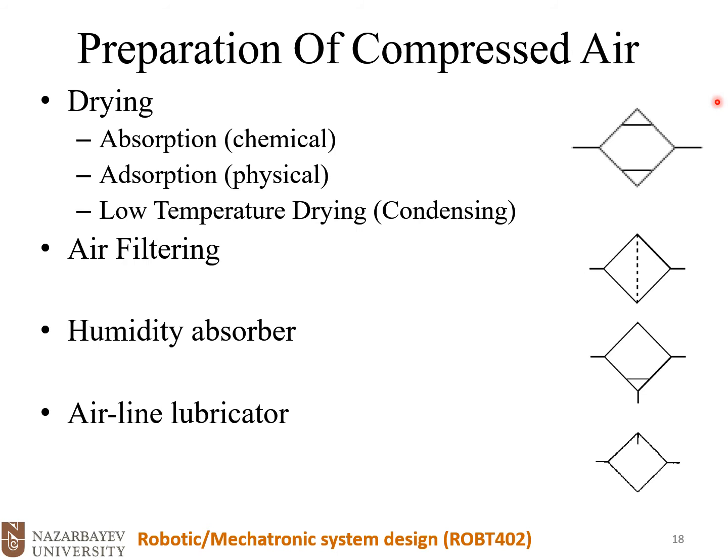We could have a drying unit. That drying unit basically will remove the humidity of the air. We have different types of drying units. Absorption, which is basically a chemical reaction. Adsorption, which is a physical reaction. We have low pressure drying or condensing.